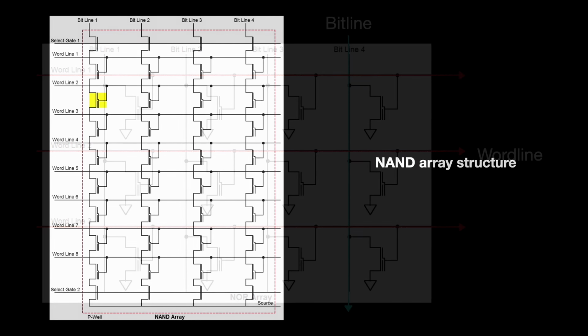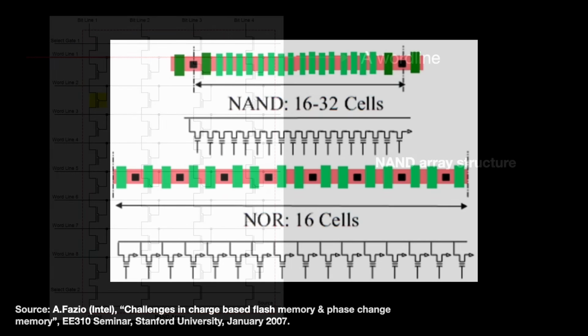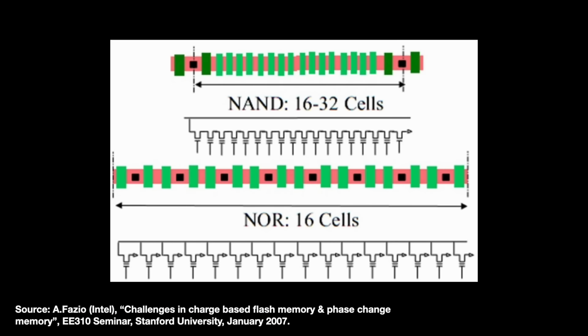With NAND, we have 16 to 64 memory cells connected together. Each of the cell's control gates are connected to word lines, like with NOR, though that word line is shared amongst all the cells at that position in the array. The bigger difference against NOR is that most of the cell's drains are not connected to a bit line, but rather to the source of its neighbor cell, creating a string. The only bit line is at the end of that string. There are just 2 contacts in the whole array at each end, which saves a lot of space.